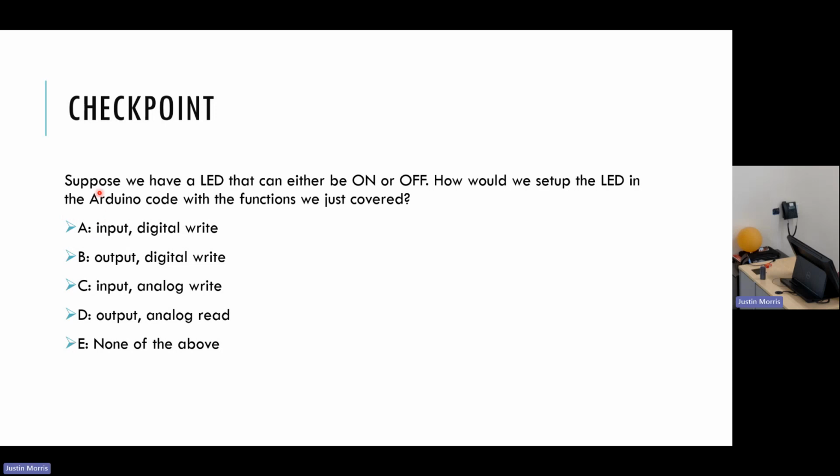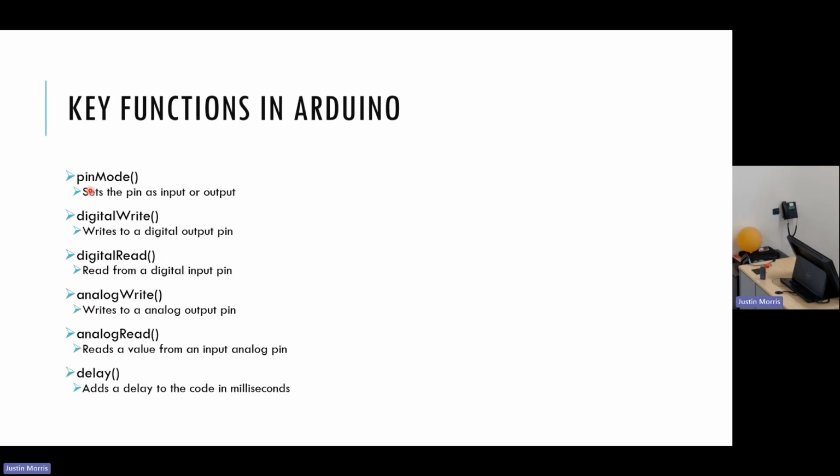And we are going to do this in the first lab. So the first lab, you're going to download the software, Arduino IDE. And the very first thing you're going to do is connect an LED with a resistor to the Arduino board and turn it on and off. And it's mostly just to get you started with connecting things to the Arduino board through the breadboard and using these functions in the Arduino code, as well as verifying that your Arduino IDE install is working properly.